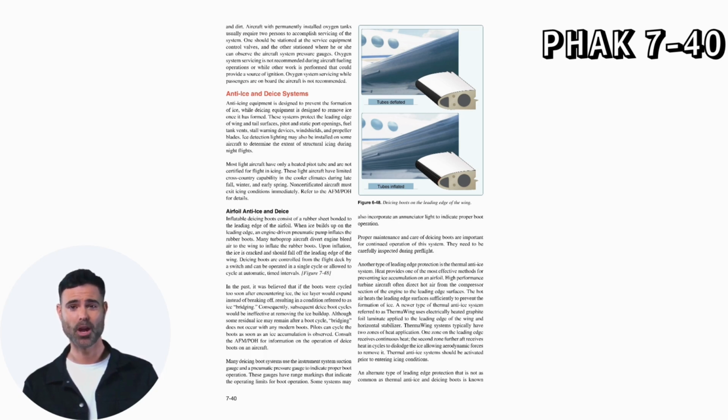Although some residual ice may remain after a boot cycle, bridging does not occur with any modern boots. Pilots can cycle the boots as soon as an ice accumulation is observed. Consult the AFM-POH for information on the operation of de-ice boots on an aircraft.